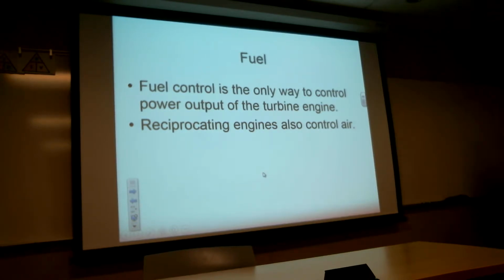Yeah, you have detonation in a reciprocating engine. You wouldn't have it so much in a turbine engine because the pressures are always going to be pretty even and the fuel is going to be metered according to the air pressure that moves into the combustion chamber. So as long as fuel is being added, you have the temperature from the compression of the air, but you also have the temperature that's coming back off of the containment that is the combustion chamber. So that temperature is going to cause it just to continue to burn.